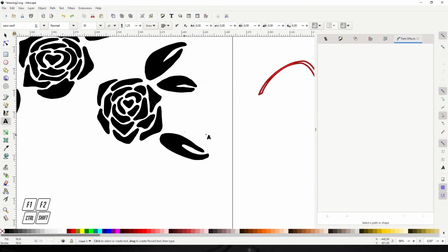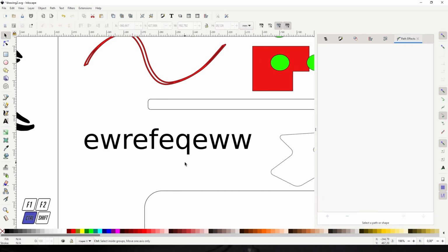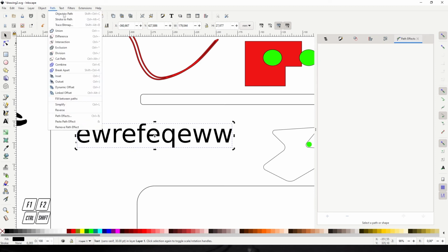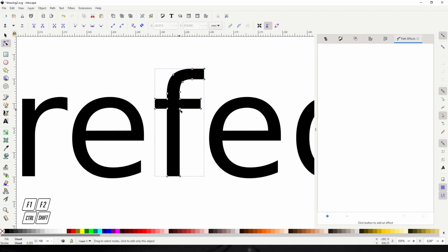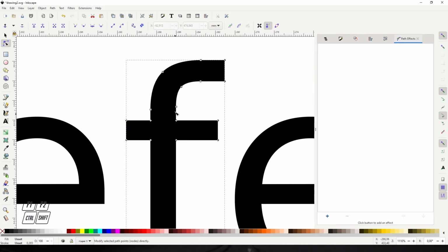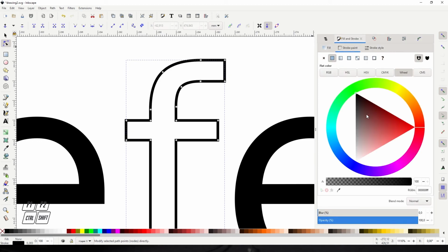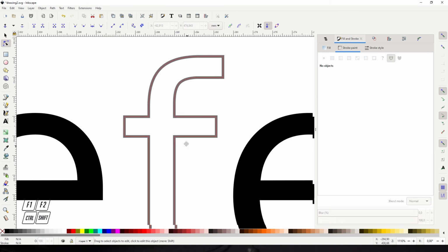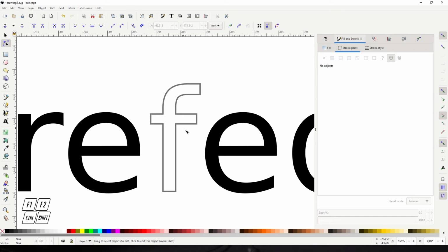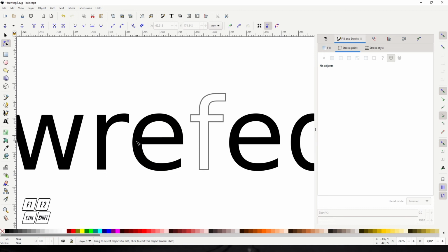So usually, if you write some letters over here, I'm gonna scale them up a bit. And as mentioned in the previous video, we'll have to convert this into a path to be able to cut it. The thing is, each one of these letters is a closed shape now. This might be what you want. You could, for example, set this to an online cut by removing the fill and setting the stroke to gray. And now cut this with a V-cut engraving bit. But what might also be what you want is that each of these letters is one single line. So if I stay with this E, for example, this way and then around the corner, and that's it.